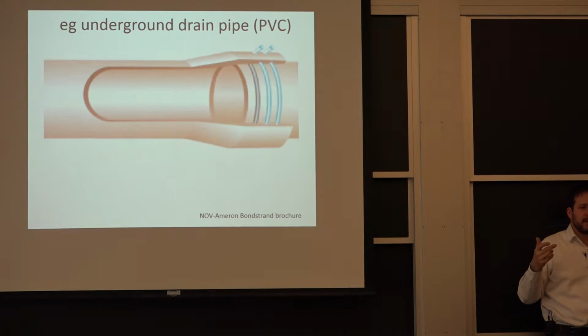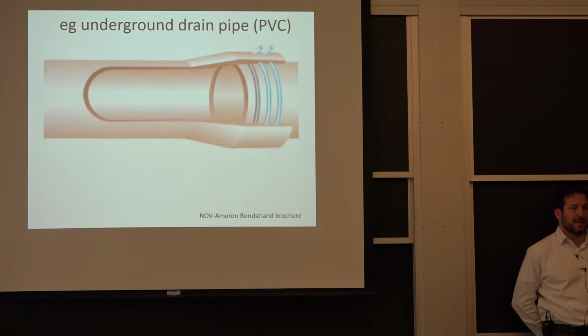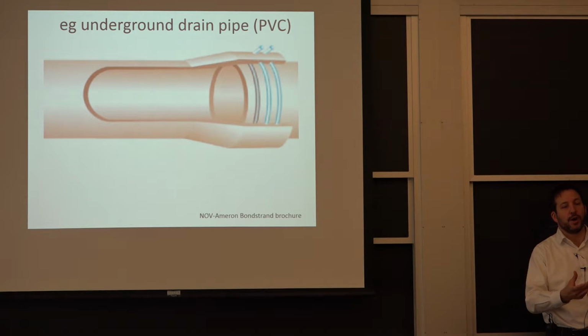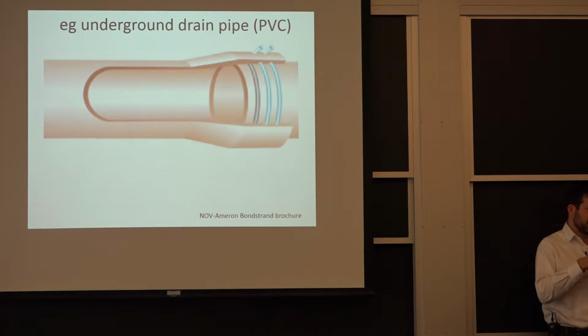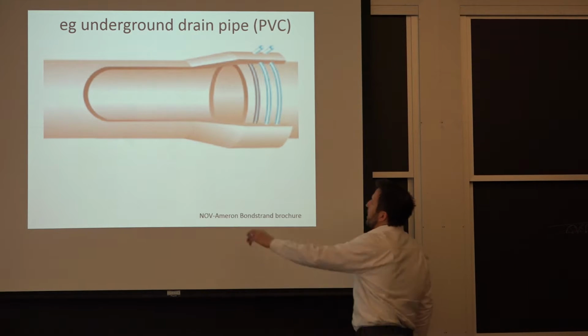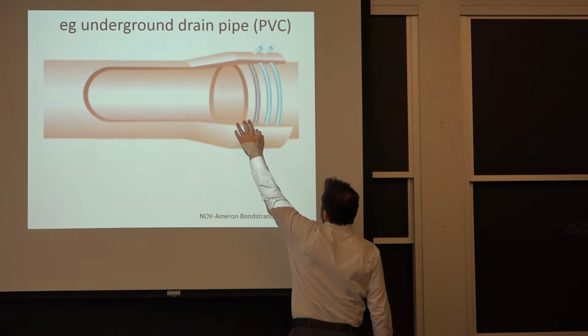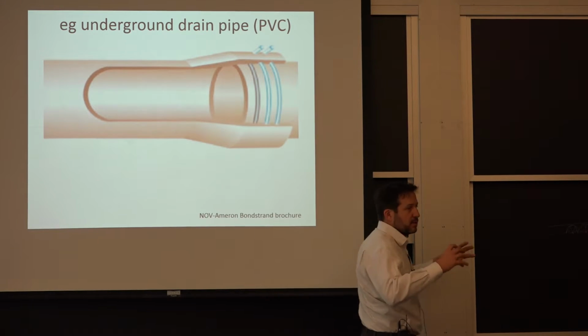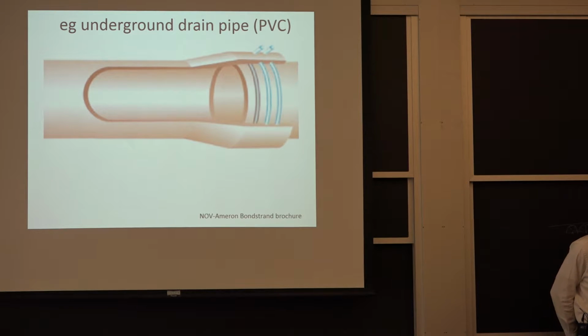And the way it typically works is you'll hold a few of those at certain distances, especially if you have to turn, if you have to put an elbow, you have a support there that stays fixed. And between the supports is where you want a certain amount of expansion. But yes, you don't want this to be completely free-floating everywhere. You don't want to put that specific joint into a building, for example. So just the ground itself is holding it in place. And you try to have about, depending on diameter, maybe 1 inch here of extra space to continue to insert. Very good question.